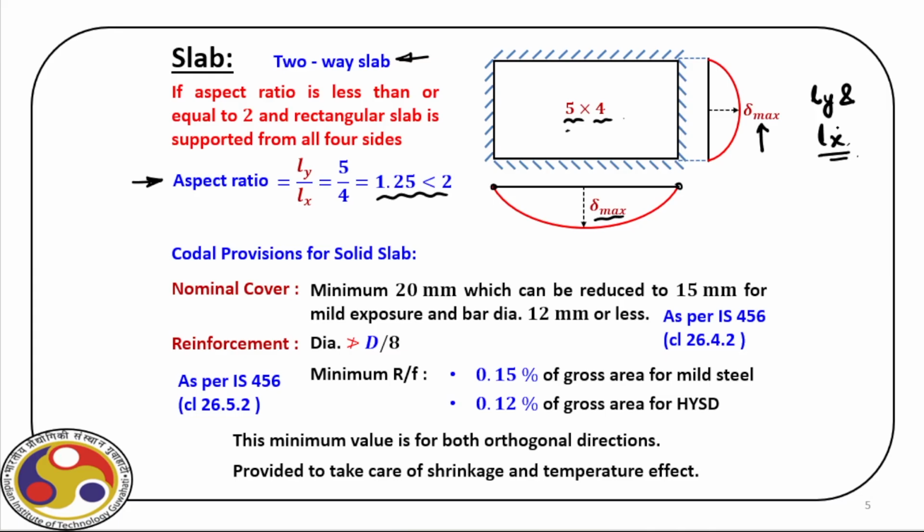Now, for this slab design, in case of a beam, you have noticed we have, say, this rectangular section, and these are the rebars. So this is what we call clear cover. In case of a slab also, we need to provide clear cover. We need to provide this reinforcement along the tension zone, and obviously we have concrete to take care of compressions.